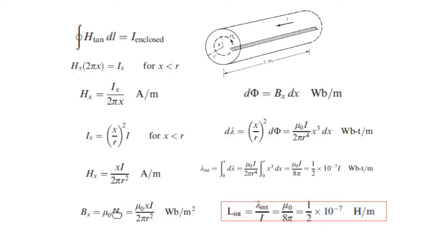The conductor is going through this one, then the magnetic flux is around, like this. If the current is going this way, then the magnetic field is on the other side. Okay, so from the flux density, Weber per meter squared, we then get the flux itself. Phi here is the flux. From the flux, we can get the flux linkage, as you can see here.